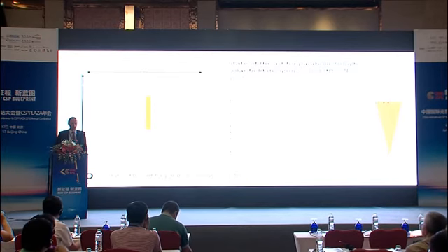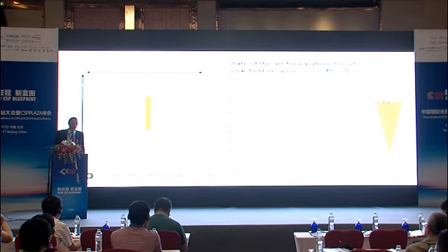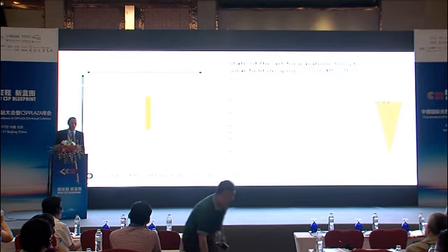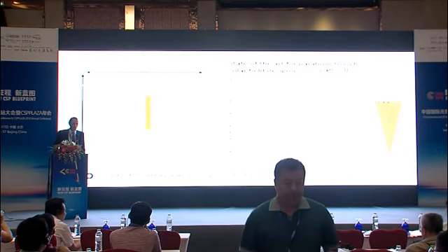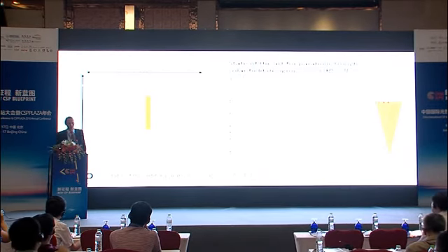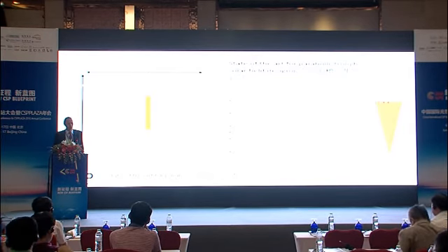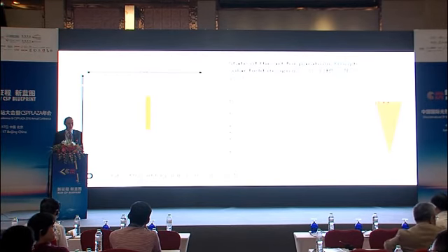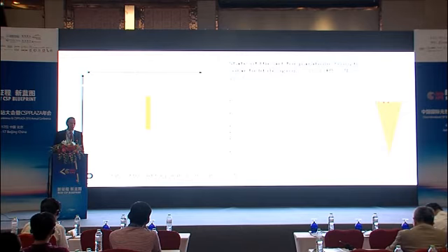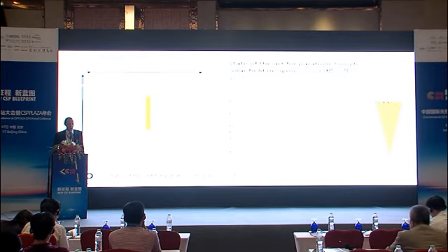Not in desert regions, because there the land is so cheap, but there are many locations where you're cramped in the site and usually your site boundaries are not north-south. So it's not a problem to turn your solar field to a different orientation and work with the boundary conditions provided. And actually, if your daily profile of DNI is not the standard one, it might even improve the solar output of your solar field. So I think it's questionable to always do it like that without considering what could actually happen.